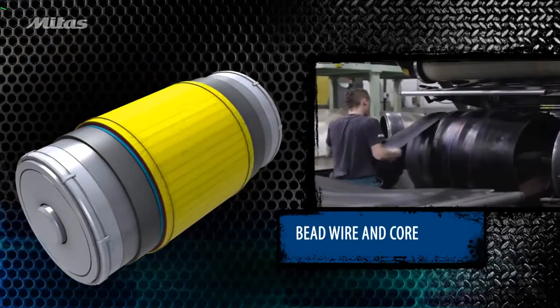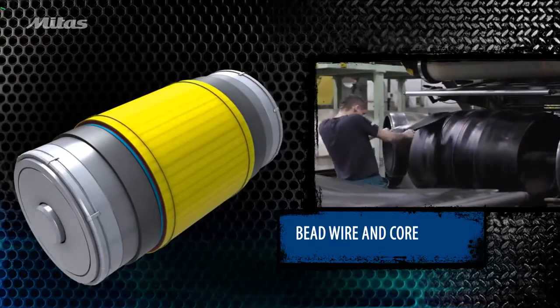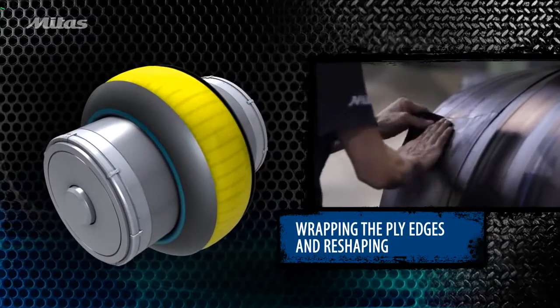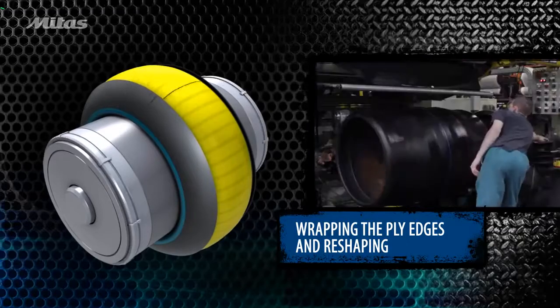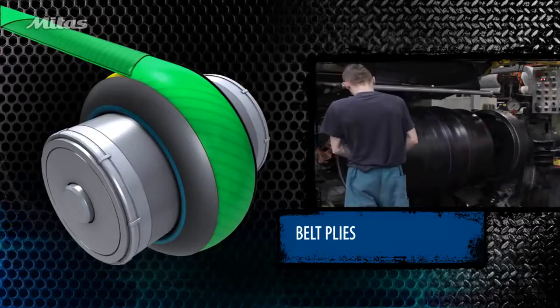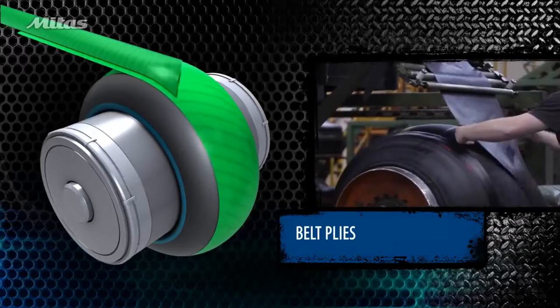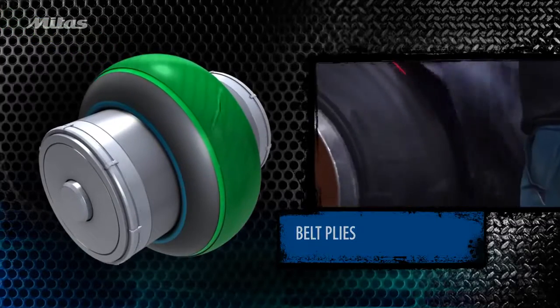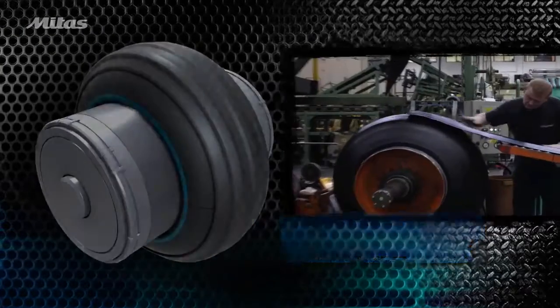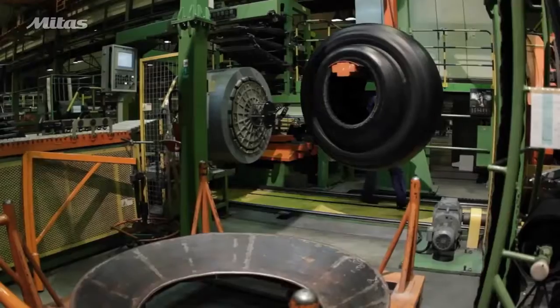Bead cores are placed on the building drum. Then the ply edges are wrapped around the bead core and the sidewalls are moved into position while the tire is reshaped. After inflation, the belts and tread rubber are applied. For large tires, the tread rubber is wound onto belt plies. This process achieves a green tire that already resembles the final product.